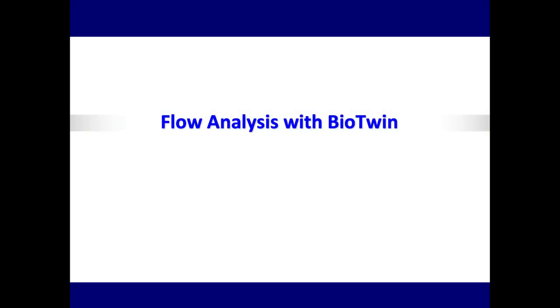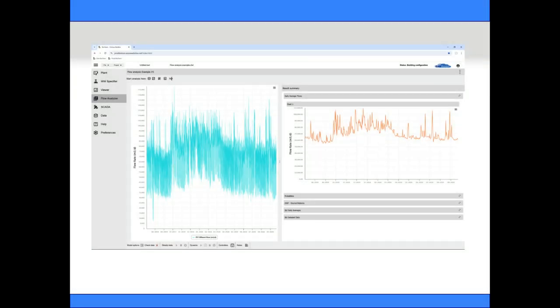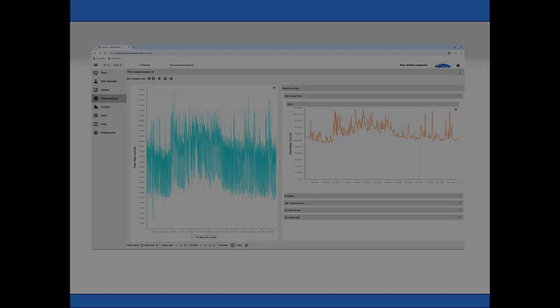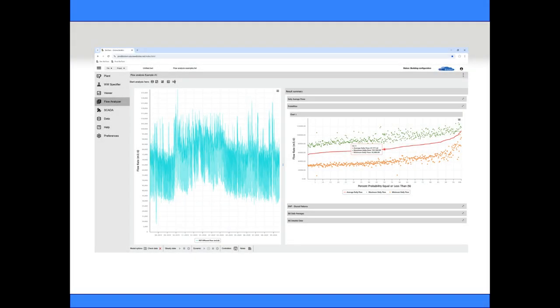In treatment plant simulation, usually we are concerned with applying realistic diurnal influent flow patterns characteristic of the particular plant. Also, we likely are interested in knowing about the extent and seasonal nature of excess I&I flows, in addition to the diurnal municipal flow. Extracting this information from historical SCADA influent flow data, for example, measurements at, say, 15-minute or 1-hour intervals, is a very tedious and time-consuming exercise.